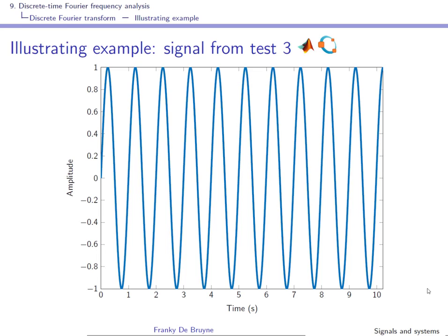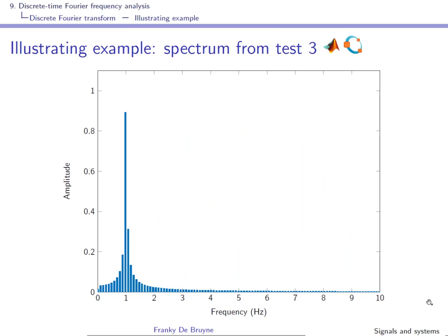And remember that if you take the discrete Fourier transform, this is going to be seen as the discrete Fourier transform of a signal that is repeating itself indefinitely, and this will cause discontinuities that go from 0 to 1, and this will lead, of course, to spurious frequencies appearing in the amplitude spectrum. This is indeed what you can see in the amplitude spectrum of the third signal.